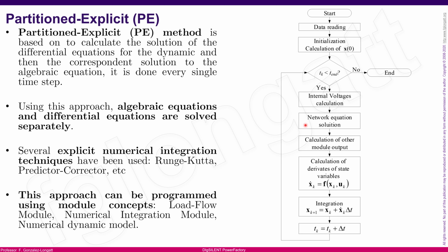Okay, but if we go into the classical transient analysis, when we are interested in calculating the initial conditions, what we are doing is calculating, for instance, several variables that are extremely useful for the transient. One of the very important variables that we need to know is the internal voltage of the synchronous generator.